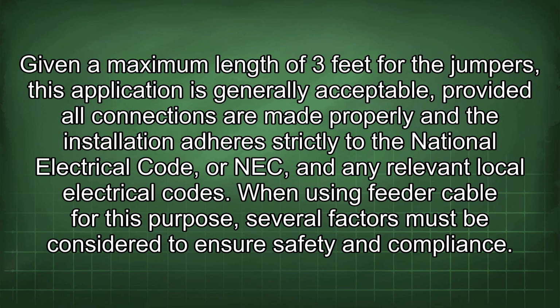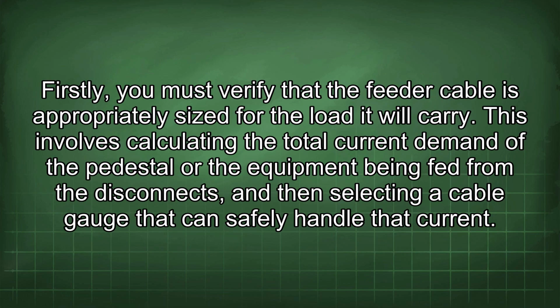When using feeder cable for this purpose, several factors must be considered to ensure safety and compliance. Firstly, you must verify that the feeder cable is appropriately sized for the load it will carry. This involves calculating the total current demand of the pedestal or the equipment being fed from the disconnects, and then selecting a cable gauge that can safely handle that current.